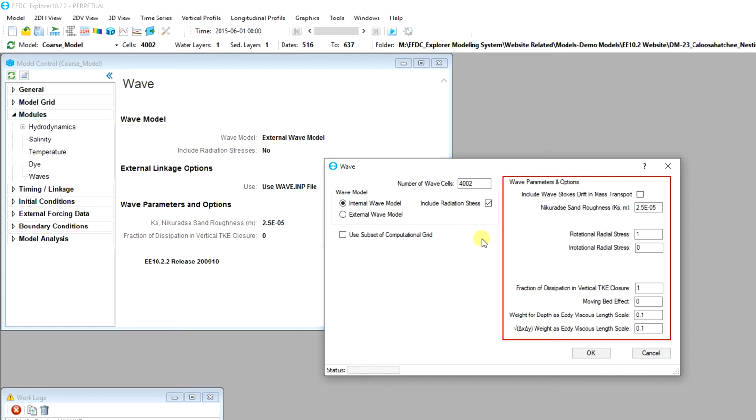The time series for wind speed and direction are used to compute the instantaneous values of wave parameters, with fetch calculated for each cell in 16 directions. The effect of shoreline and EFDC+ internal masks are included in the fetch calculations. The resulting wave parameters are then used to calculate total bed shear stress, with bed shear stress linked to the current generated shear stress via the Grant-Madsen approach.